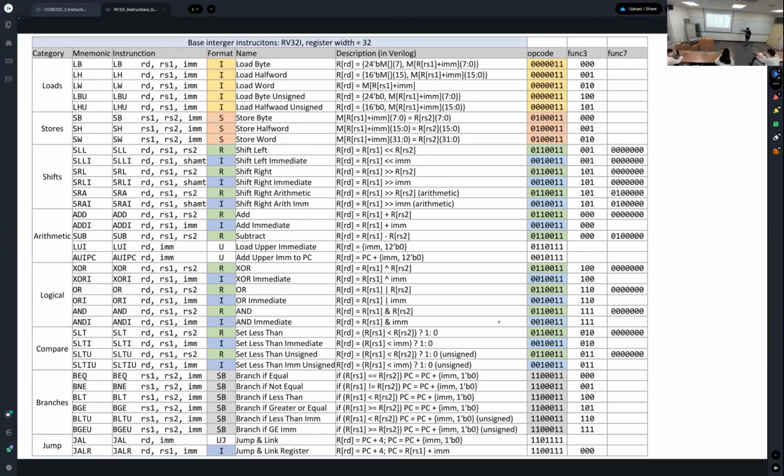Sorry, it should be a signed number. Okay, and we can also use -2, something like that. Sorry about that. So we can use a signed number for the offset. So this is the signed number. This operation is performed and then the address is generated. With this address, the load instruction accesses the data in the main memory and then transfers the data to the register file.